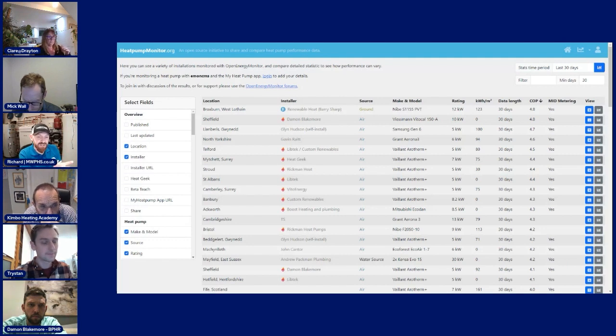But it fascinates me the amount of people on that list. I don't know how many systems there are. 1, 2, 3, 4, 5, 6, 7, 8, 9, 10, 11, 16 odd systems on that page, and they're all above a COP of 4. That's amazing. And there'll be a vast range of different flow temperatures and internal temperatures as well, so it's not like one spec. There'll probably be some there that are at a higher flow than 45-ish. Like I say, it's just that important to get that design right. That's where you're going to majorly lose or gain these efficiencies.